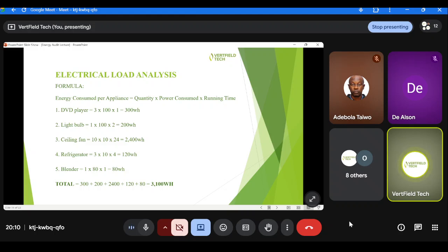Even if you are writing, I don't think you need to disturb yourself with that, because it is also available in the training manual, so you might not need to worry so much, and we're also going to make this video available for everyone. So energy consumed is given as quantity of appliance multiplied by the power consumed multiplied by the running time.